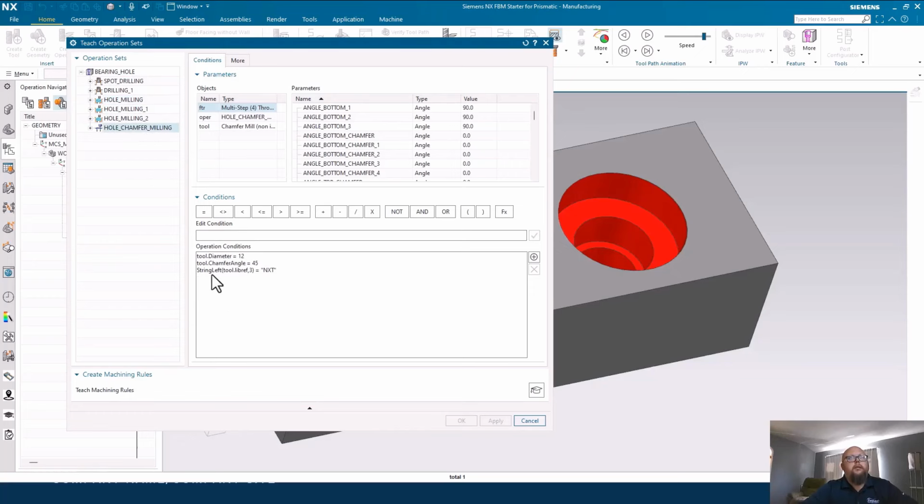These conditions are making decisions, such as what tool to use, for example. In our case, if I read this application condition, I can see that feature diameter 3 must be greater than 20 millimeters for this feature to be valid. That leads me to believe that feature diameter 3 on that 3rd hole that was not processed must not have met this condition.